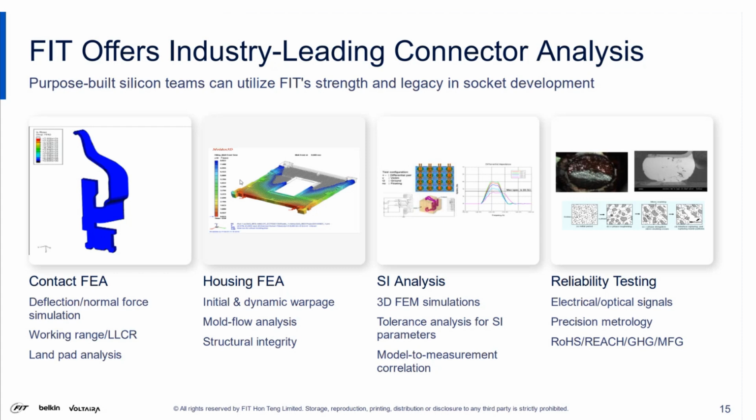So we do a lot of advanced engineering prior to even tooling up components. SI analysis: as the industry becomes more focused on signal integrity, FIT continues to grow and have leading engineers who do advanced SI simulations for both differential and single-ended pairs up into the higher frequencies that we're looking at, well beyond 56 gigahertz and beyond PCIe Gen 6, Gen 7.